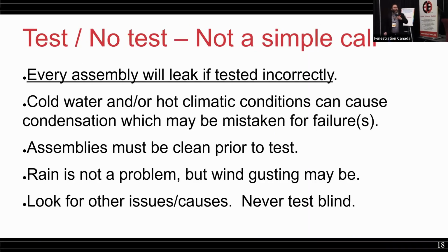So fundamentally, we don't always test when we're asked to test. That's going to sound a little strange, I'm betting, but I don't want to test something that we can't reasonably and easily clean. If it's not clean, it's not being given a fair shake at actually passing. If we are going to test an assembly, it's because we think it's going to pass. If we think we can easily tell by some form of field review that something doesn't look good, we're not going to test it. We're going to tell somebody, hey, something's wrong, something doesn't smell right. We're willing to test. You pull the trigger, go ahead. But here's the reasons that you failed our preliminary checklist. We don't think it's a good idea to test today for the following reasons.